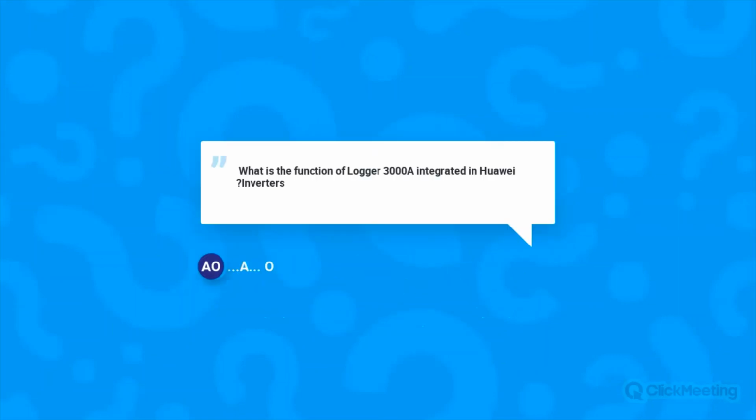What is the function of the Logger 3000A integrated with Huawei inverters? The Smart Logger 3000A is a data logger. It converges ports and protocols. It has multiple input ports and different interfaces. It communicates with the devices from the solar system. It centrally monitors all the output of the solar system and sends it to the FusionSolar platform for monitoring.